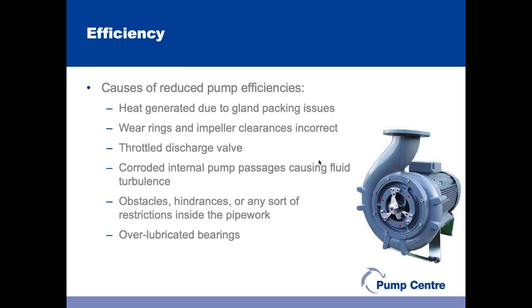Any heat that's being generated is coming straight out of the power that's being put into the pump itself, so it is seen as an inefficiency. Another cause of pump efficiency reducing, of course, is if the clearances, wear rings or impeller clearances are incorrectly set. Many pumps rely on those clearances being as small as possible, and if as a result of wear they're increased, then that will be seen as a drop in efficiency.